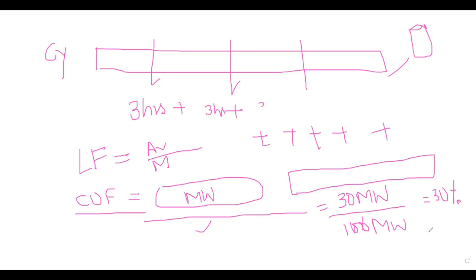Generally, for solar plants, the capacity utilization factor is 19%, 20%. For wind, maximum you can see 30%. Because these are not raw material based, these are non-predictable. Even in the summers, sometimes due to cloud passing, the generation of solar comes down. You cannot expect high generation even in the summers, and this cannot be predicted. These are seasonal changes.